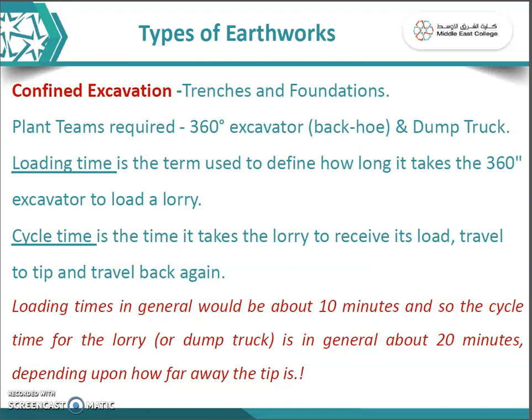So it is called a tip. The time taken for this tip is generally known as cycle time, as we discussed in the previous class. When the truck goes to the dumping area and comes back, the excavator should not be kept idle. So we have to arrange at least 2 trucks, so that when one truck goes for dumping, another truck can start loading. This is a cyclic process.